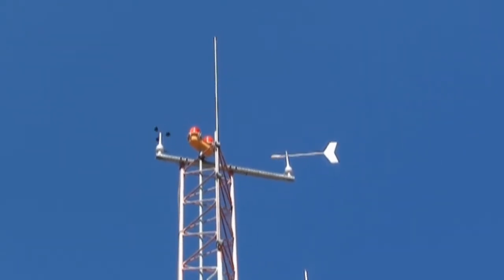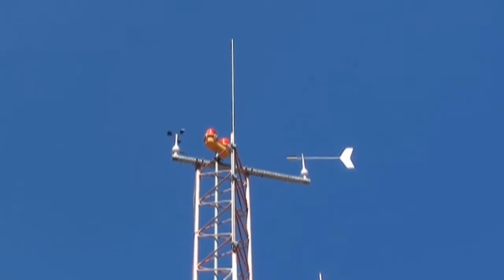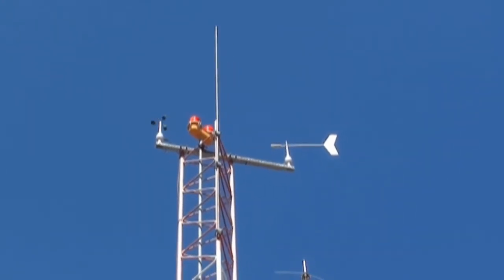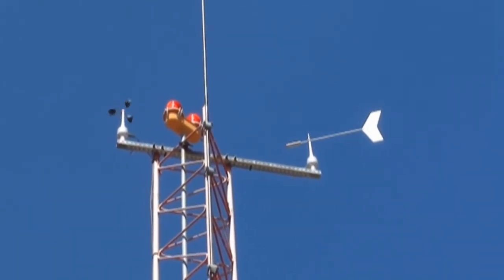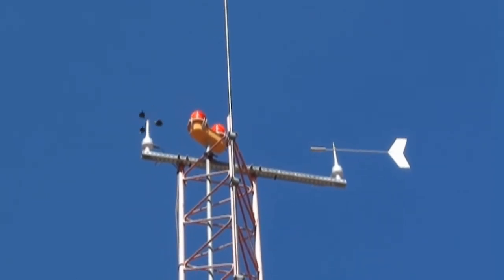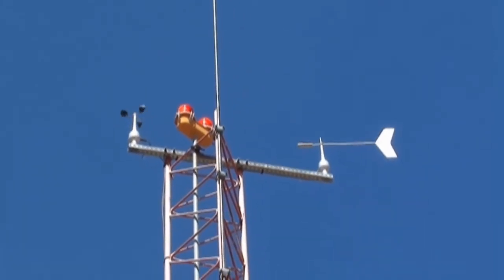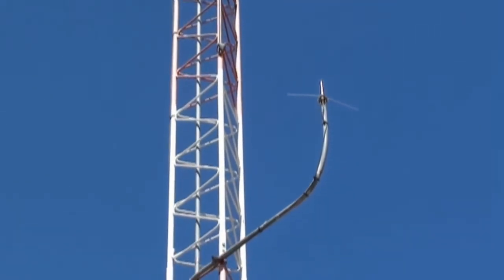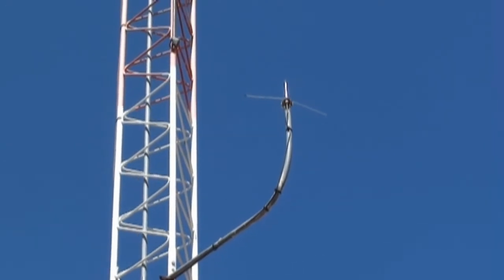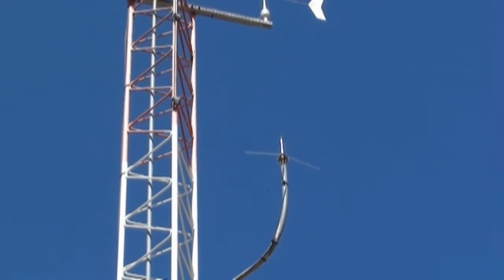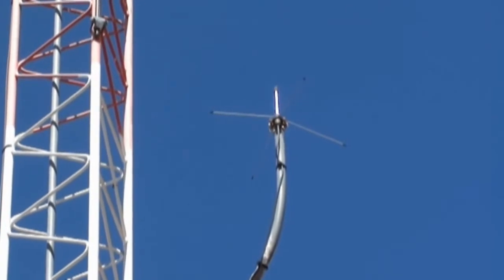At the top of the tower outside, located at the northwest end of the field, we can see several components. There is the wind direction vane sensor and the wind speed sensor twirling, the red obstruction lights to warn pilots of the tower's height, and the lightning rod to protect the electrical components here. The small 4-pointed star at the end of the S-shaped pipe is a UHF antenna used to transmit the raw data back to the control room. This data is electronically translated by the control equipment and broadcasted to the pilots continuously in a voice format.